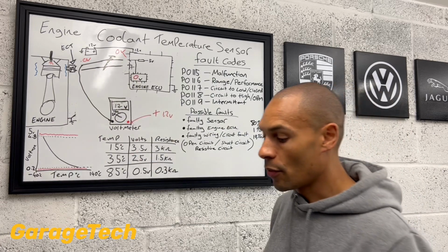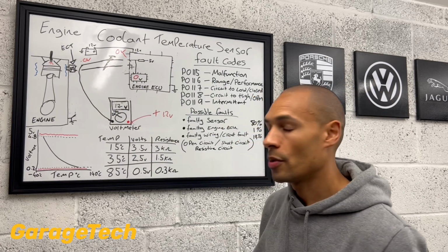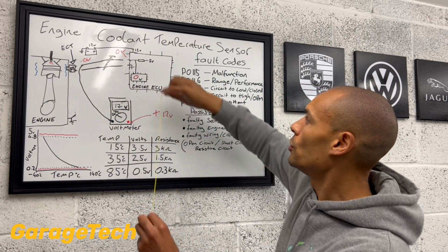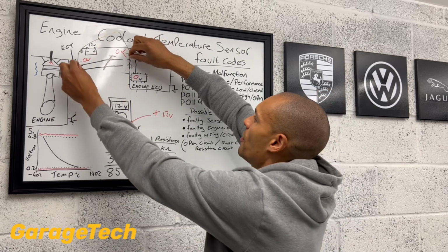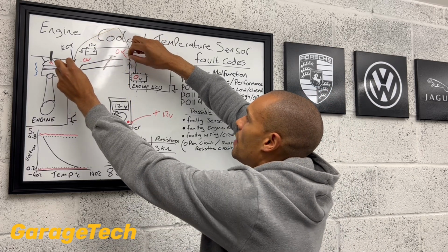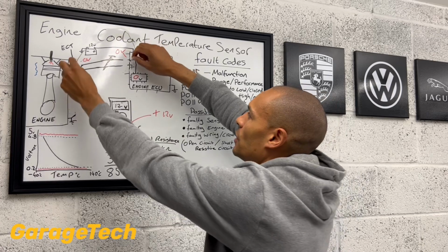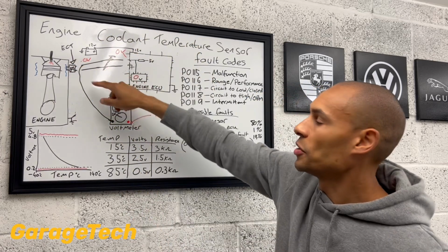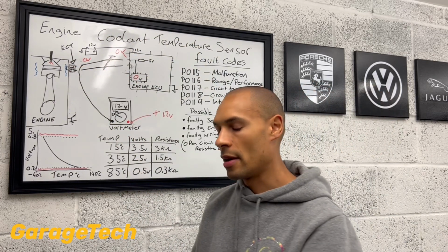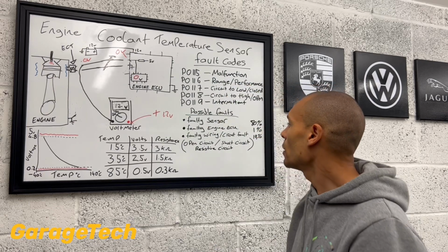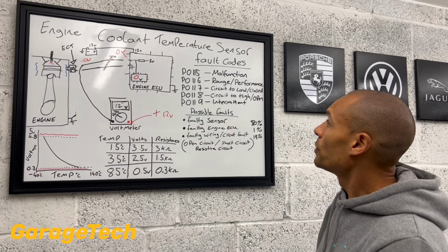And again, if all fails, what you can then do is do an overlay and run a new piece of wire basically between there and there. And then that will give you a confirmation that actually, yes, you definitely know there's a fault with the piece of wiring, the original piece of wiring that's there in the car. Okay, so that kind of covers off those.